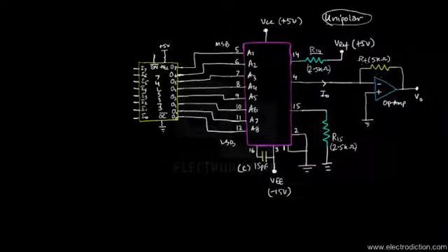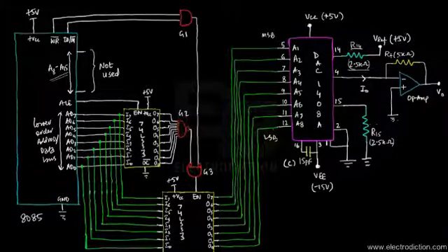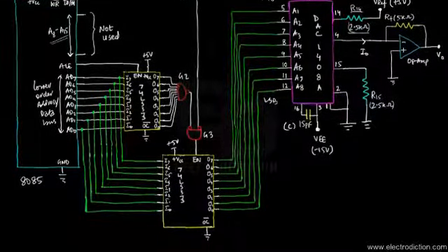And finally we need to interface, or rather connect, these two with the 8085 microprocessor circuitry. Let's take a look at how we do that. Alright, here we are with our designed hardware. As you can see in this circuit diagram, we've got the 8085 connected with its latch chip, the 74LS373, for latching the address coming from its lower order address data buses, AD0 through AD7, and on the right hand side we have the DAC 1408A interfaced with the 8085 microprocessor by using the latch LS373 in the very same way that I just told you.